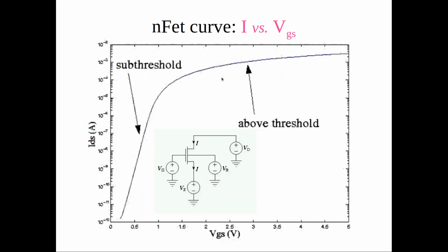And as I said, most courses teach, historically, from the 80s on, the analog design courses are teaching how to use transistors in this region here, where you have relatively large voltages and relatively large currents, milliamps, 10 to the minus 3. And the reason is that if you have some signals that are noisy, if you're doing analog, you want to do your hi-fi equipment, and if you have some noise, which is making your input oscillate, say between 3.5 and 4 volts, you have some huge noise here. The effect on the output is relatively small. You're compressing the noise.